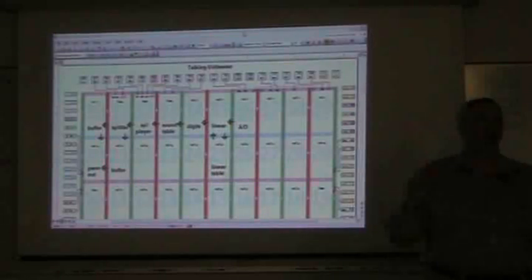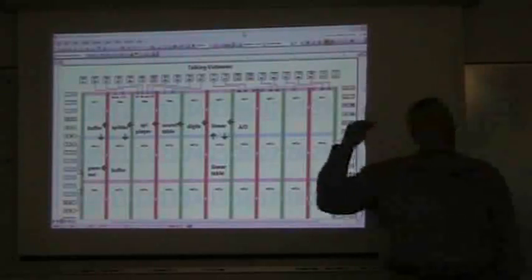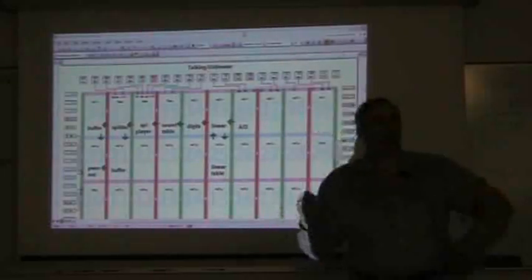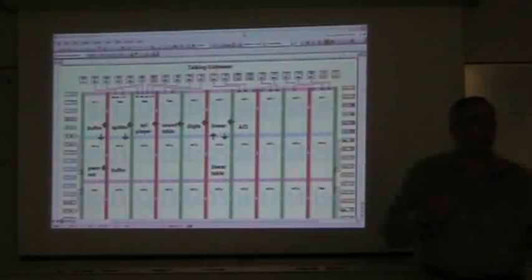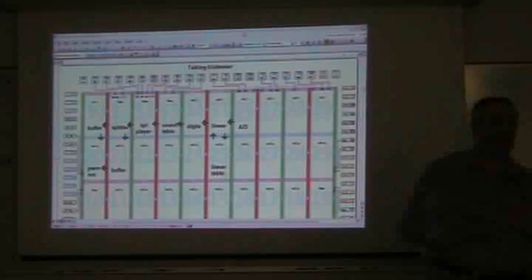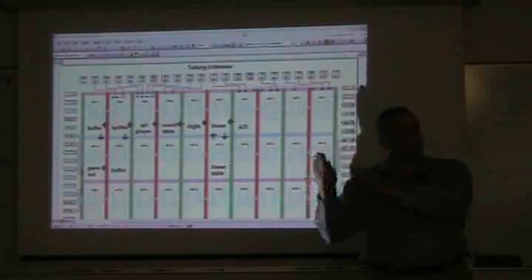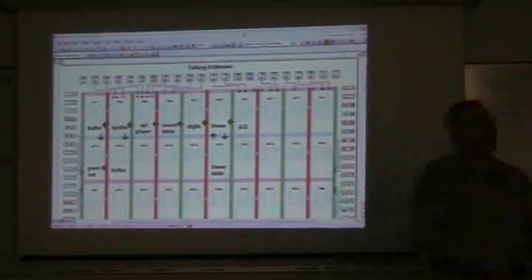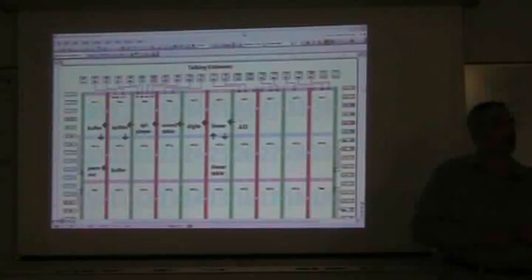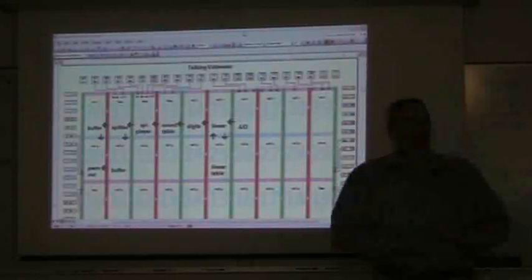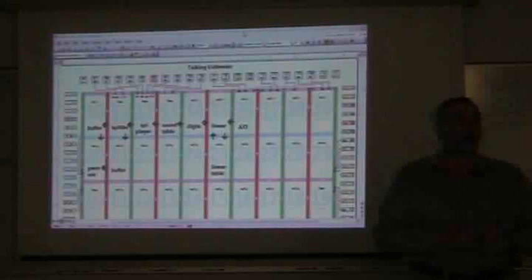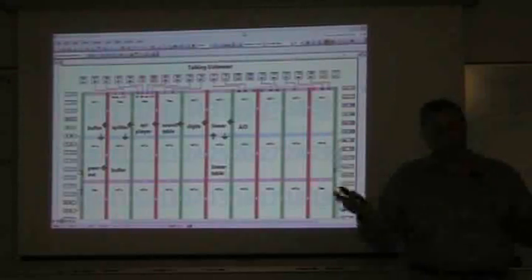And I will say on the video application, I have one table, which is a table of voltage count from the VCO into voltage out for the D to A. And it takes care of linearizing both the input and the output at the same time. So that we bring it in from a nonlinear device, put it through this table, bring it out, send it to a nonlinear device, but it turns linear in the process. And you can calibrate that table. For instance, if you want a negative image, if you write the table inverted, the output image suddenly becomes inverted, and that's all you have to do to it.